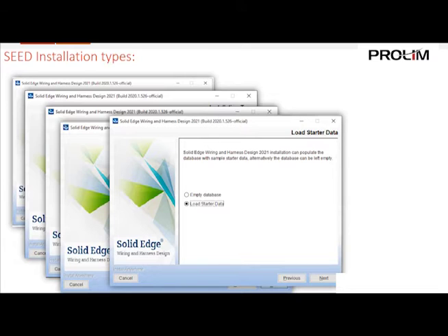But just another side note here, if you chose to do IEC and then you find out later down the road that most of your symbols are in the ANSI industrial standards, you can always change that after the installation is complete. So I'll show you that briefly in a demonstration where you can access all that. But just keep in mind that you can always go back and change it without having to do a whole new install to get access to those other industry standard templates.